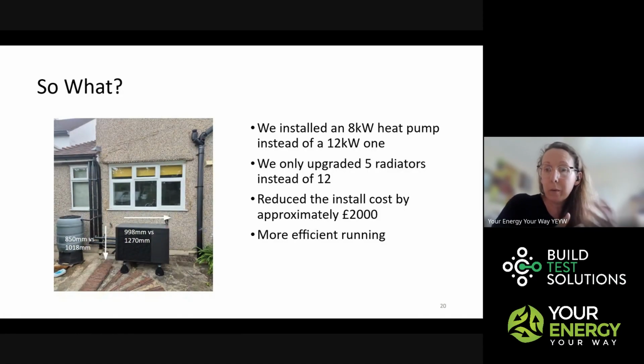It's really useful to be able to go back and check that you're achieving that, because if you've oversized the heat pump, the flow temperature will be an awful lot lower. If you've undersized the heat pump, you will know about it because your customers will be cold. So I think it's the oversizing that's harder to find out if you don't have the data to go back and take a look. So yeah, that's all from me.